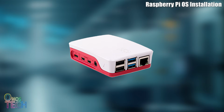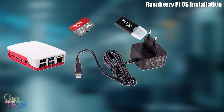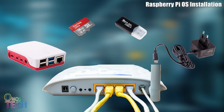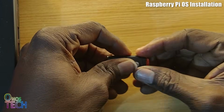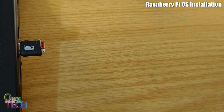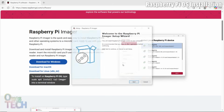To set up the gateway, you will need a Raspberry Pi 3, 4, or 5, a 16 GB plus micro SD card, power supply, Ethernet cable, or Wi-Fi hotspot, and of course, your laptop or PC. We will do this entire installation headless, meaning no monitor, keyboard, or mouse is required. Now, insert the SD card into the card reader and plug it into your computer. Head to the Raspberry Pi software page to download the Raspberry Pi Imager for Windows, in my case, and run the installation.